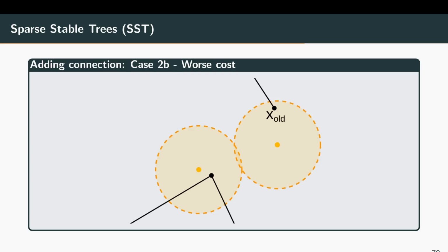But in general, because we're in kinodynamic motion planning, isn't the exact position of the point also relevant for any future expansions? Let's say my cost function for this old point will be very low to my goal because maybe I'll just go straight forward. And my new point maybe has a lower cost up to that point, but then from there to go to the goal, maybe I have to do a turn, which will have a higher cost. What will happen in this scenario?